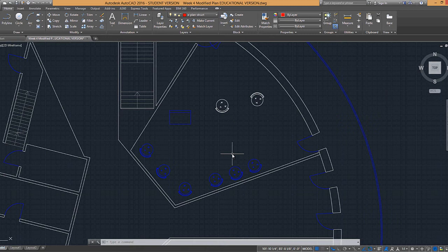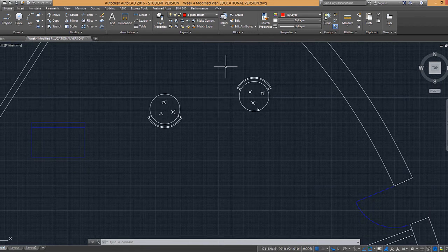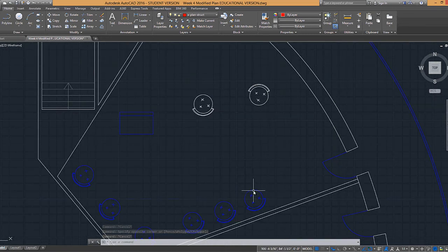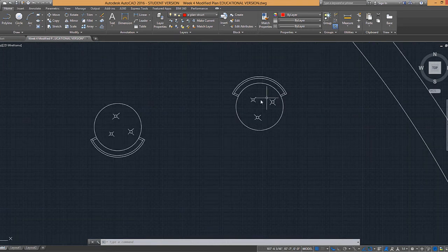You can also export parts of your drawing to an external file for further use as a block file to be inserted into other drawings. It doesn't have to be a block, it really should be the original objects, because if I create a block from a block, you're going to have to explode it and explode it in order to get the original objects back. So this is something I would want to do with my original objects.